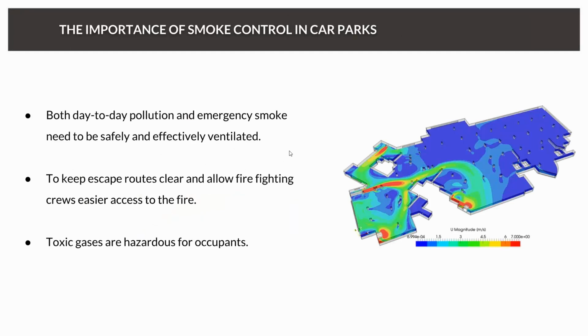And on the right side you can see, for another car park, the simulation results. Here we have a slice half a meter above the ground, one meter above the ground, which is representing the actual flow velocity. And you can see these jets of the HVAC inlets and also how the air is moving through the space and removed here, for example.